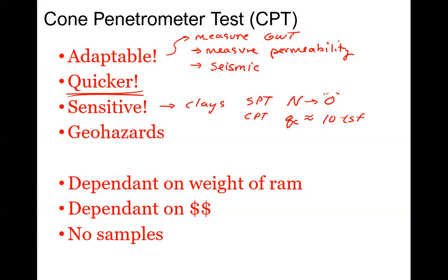Cone penetration tests are really popular for geohazards. Especially sinkholes, we're starting to use that a lot more because it's a quick test and also less intrusive. If you have a potentially forming sinkhole, you aren't hitting it with a hammer. You don't want to use a super intrusive test and washing all this liquid. So we use a CPT, a nice quick and less intrusive test, for sinkholes, and then also for liquefaction, so for earthquakes, and for landslides. Due to its accuracy, we can pinpoint the exact location in a subsurface profile where a landslide may potentially form, like a slip plane or something like that.